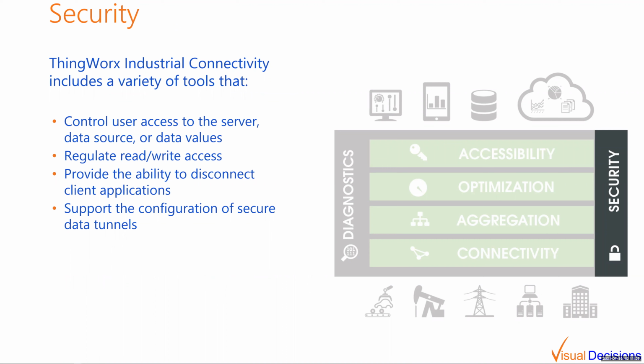From a security perspective, it includes a variety of different tools that expand administrators' abilities to control user access and regulate read-write access for secure data communications. It supports a number of secured client standards, SNMP, OPC, HTTPS, to further restrict access to the server. And it supports a number of secure device protocols to meet the requirements of DNP3, SNMP, and OPC UA data sources.